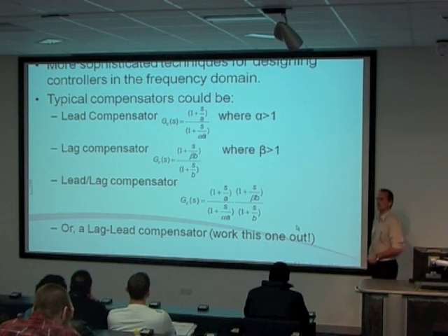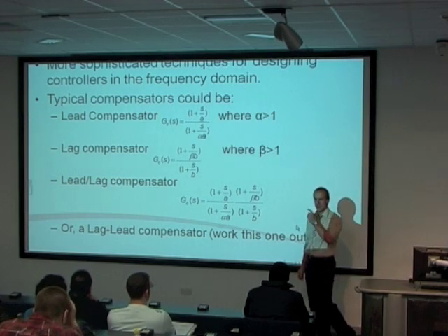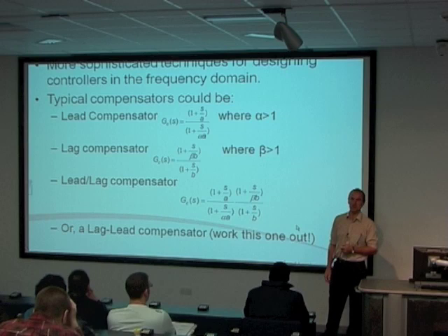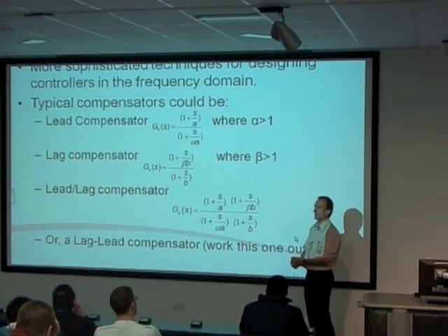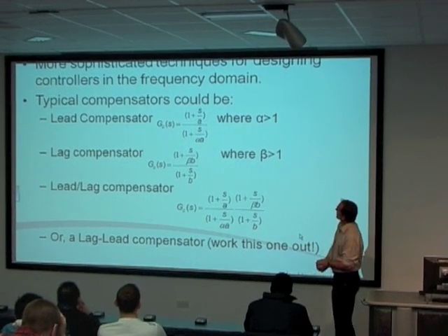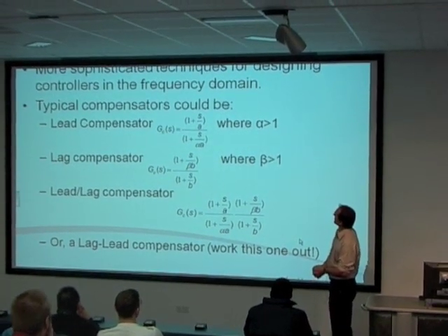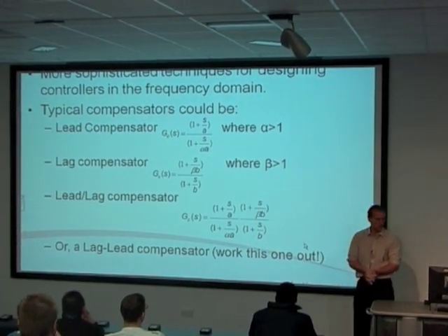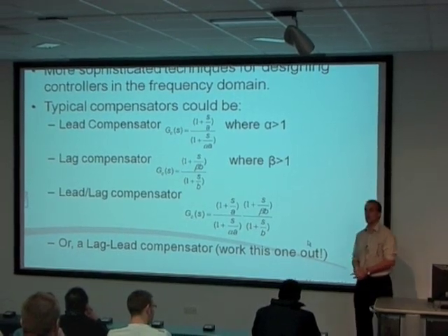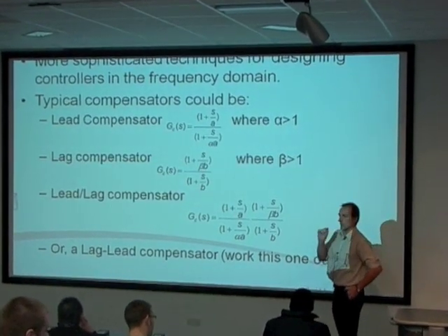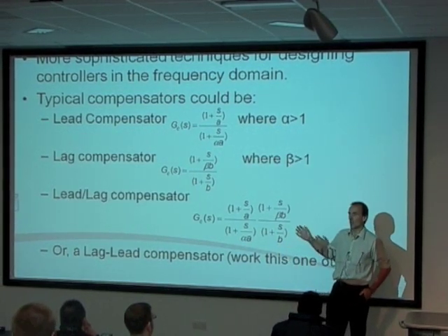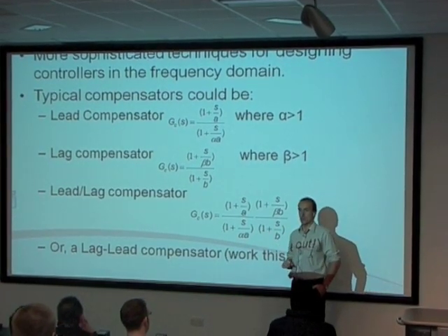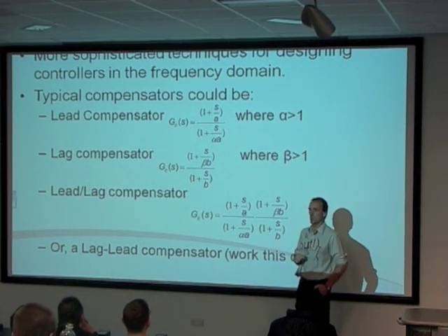That's the easy one. What else can we do? Well, we can get a bit more sophisticated with all this stuff. And instead of just crudely lifting one of the curves up or dropping it down, we can introduce more sophisticated techniques in the shape of what we call compensators. These are devices that you put in just the same way as we would that gain, in the forward path, so they appear in the open loop transfer function.